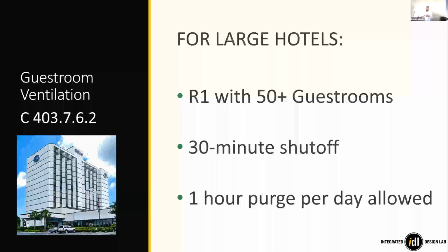We're going to manage it X way, but it has to be managed some way to provide some shut off so that we're not bringing in tons of outdoor air to rooms that are just vacant over a long time. But that 1 hour purge per day should also count for the hotel staff doing cleaning and making sure that we get the chemicals out as well.